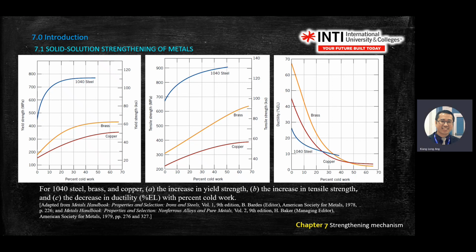Later we look at one example of how to use this graph. So it's just how you extract the information for that one. The percentage of cold work you need to apply equals the ratio of area times 100%. And you need to read carefully what the customer wants.